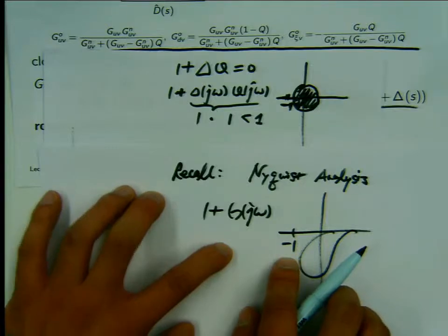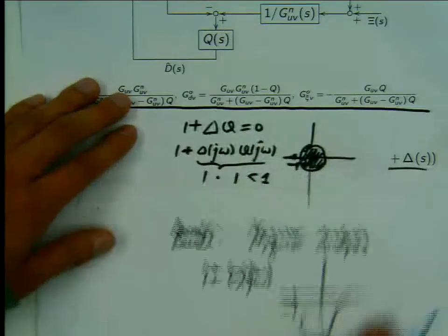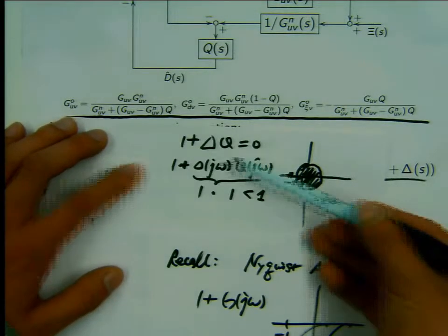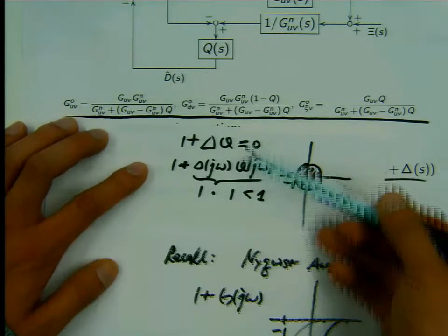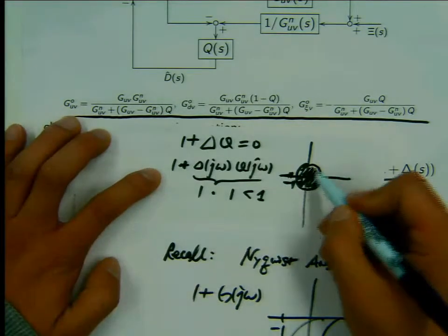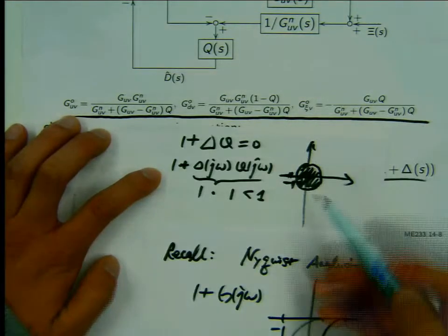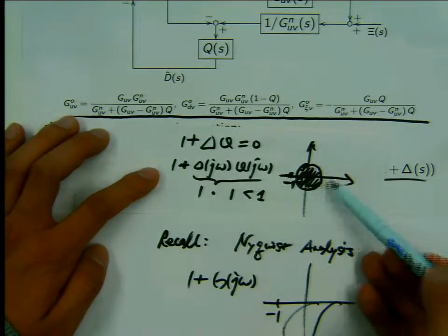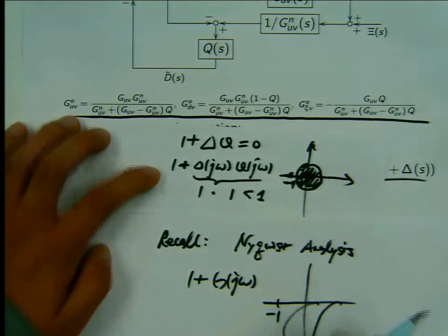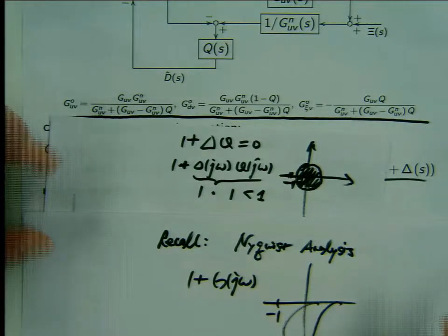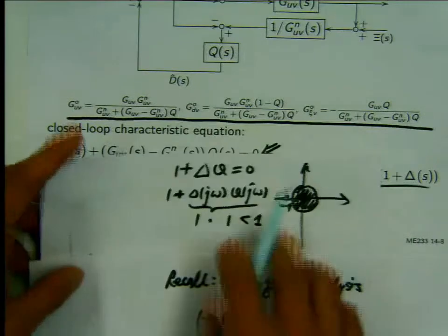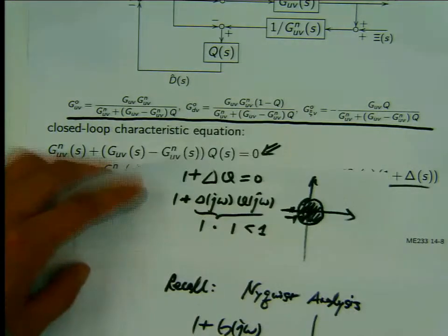It's a basic Nyquist analysis. And here, things are exactly similar. If I want to analyze the roots of this equation, take a look at this complex domain picture, then you see this is never going to be able to touch the -1 point. So that means this is a sufficient condition for the roots of this characteristic equation to be stable.